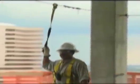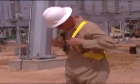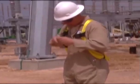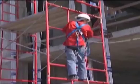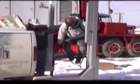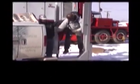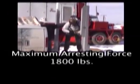OSHA defines Personal Fall Arrest System, PFAS, as a system used to arrest an employee in a fall from a working level. Each component of the system must be able to withstand the amount of impact forces involved with stopping an employee that is falling. The farther an employee falls, the greater the force needed to stop them. PFAS must limit the maximum arresting force on an employee to 1,800 pounds.